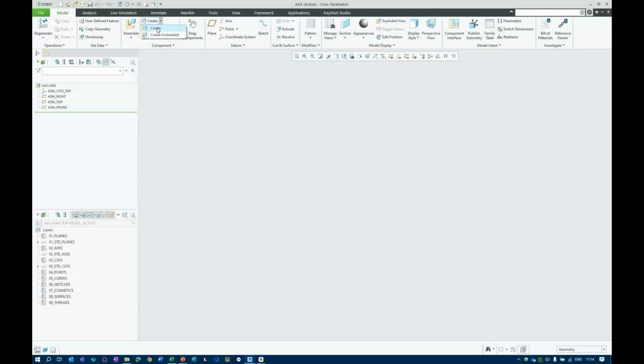So I will create a skeleton model like you see here. You'll see that it automatically takes the name of the assembly underscore skeleton. So in naming in your bill of materials, you see that they are listed together as well. The second thing that you see is that it's placed automatically on top. It's always default assembled. You have no choice in that. And it's the first thing that it starts calculating. And that's important. If you change anything there and then you push it downstream, it's the first thing that needs to be calculated.